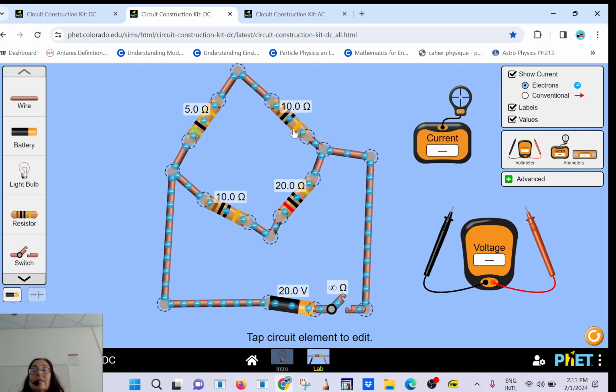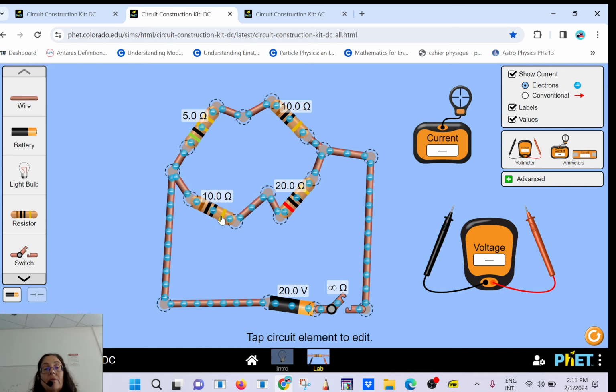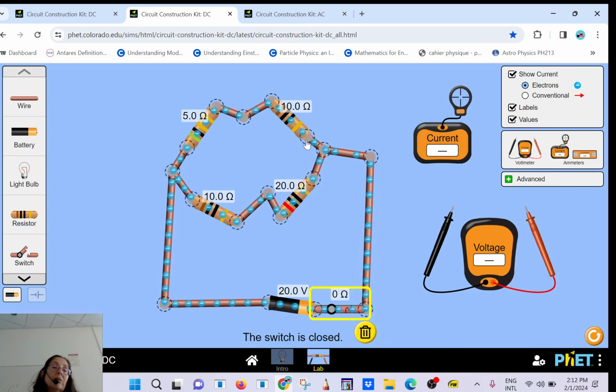So let's find the equivalent resistance of the whole thing. Don't be confused because that makes a weird angle. You can change it, right? It's still a parallel. They're in parallel, right? So you have two branches, one branch here and one branch there. Let's take care of this branch. You see there is no intersection, it's just following through. So this 5 and this 10 are in series.